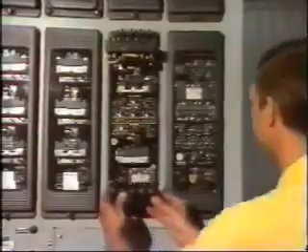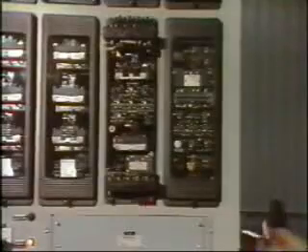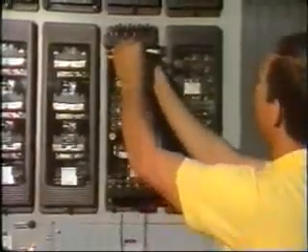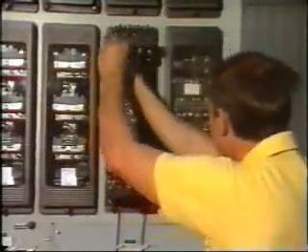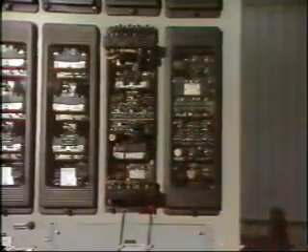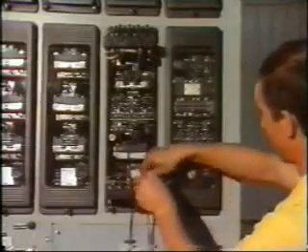We already know from earlier tapes that sensing information is provided to the protection system by coupling the relay to the load circuit through instrument transformers. Current transformers, CTs, and voltage transformers, VTs, step down the power system current and voltage to safe working levels.